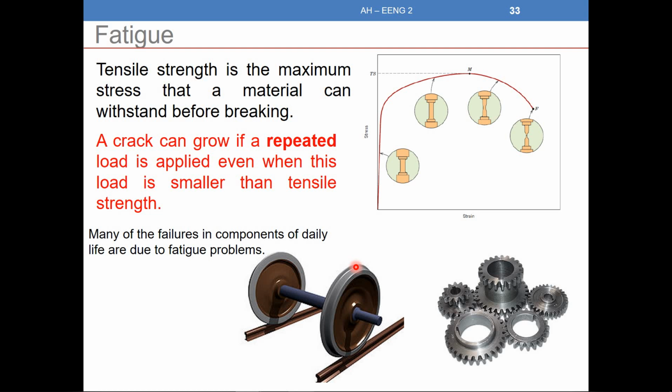So also, some reminder. What did we say about the tensile strength? Like we said at the beginning of the lecture, the tensile strength is the maximum stress that the material can withstand before fracturing or breaking. So if every time I have a stress less than the ultimate tensile strength, the material is safe, if I don't have any crack. It will not have any fracture.